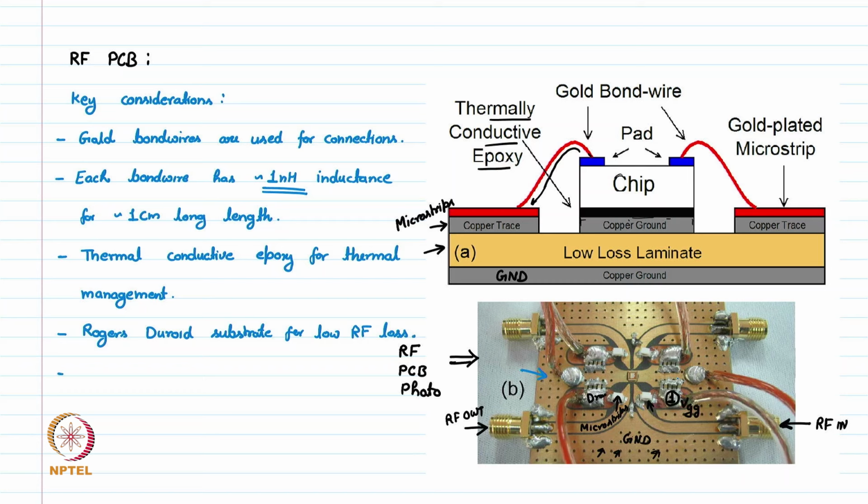We use multiple decoupling capacitors here to filter the noise from the supply rails.